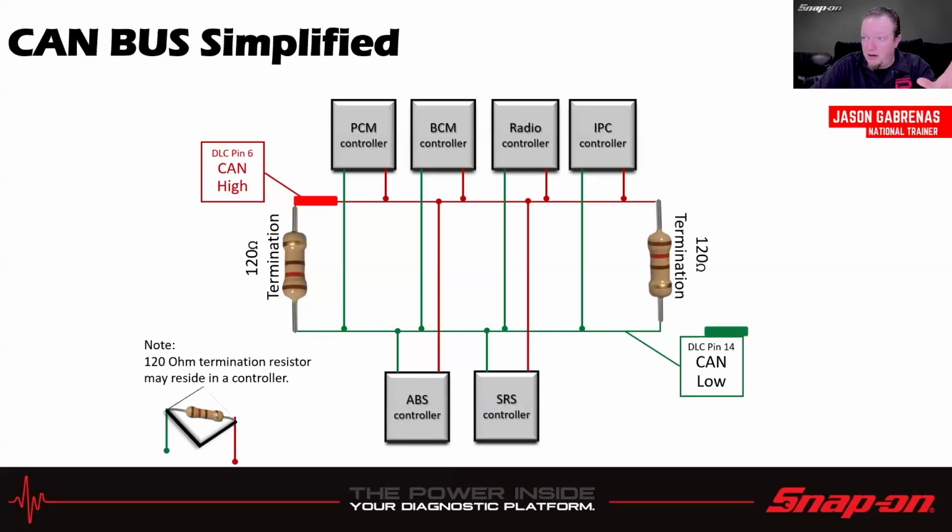So they decided to branch off into multiple buses. There were a couple different ways they could do it. They could either terminate the buses at the OBD2 port, or they can have it go through a gateway module, which would separate it out.